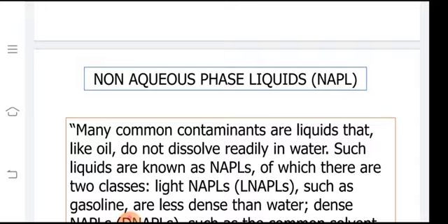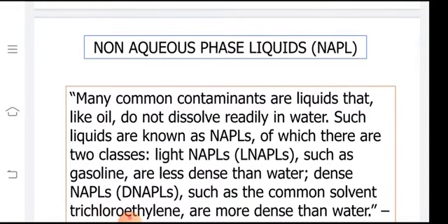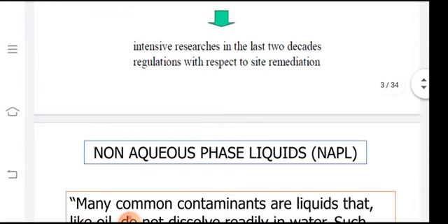Once the solute has entered the soil volume, there will be two kinds of phases we are dealing with: solid phase with the soil, and aqueous phase with the pore volumes. Later on we will talk about it, but this is important to understand the typical behavior, because it is not only one phenomenon taking place, but multiple phenomena going on. So all need to be incorporated at the same time.